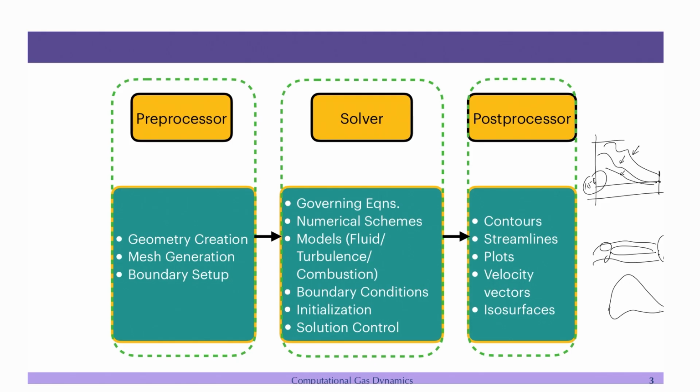So, all those kind of things you need to see, and for that the most common tools are basically plotting the contours. You can make the velocity contour or the pressure contour, density contour, temperature contour. I mean, whatever variable that you have, you can use contour. That will give you the first picture of whether the simulation is making sense.